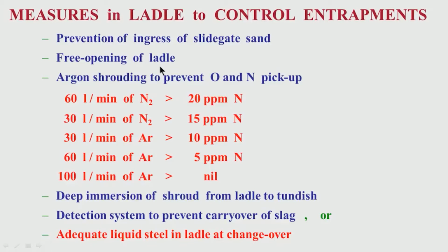Next, I have told free opening of ladle. Ladle should open free, that means when you open the slide gate, there should be opening of the ladle, that means the liquid steel should come down from the slide gate exit. So, this is called free opening. There should not be any